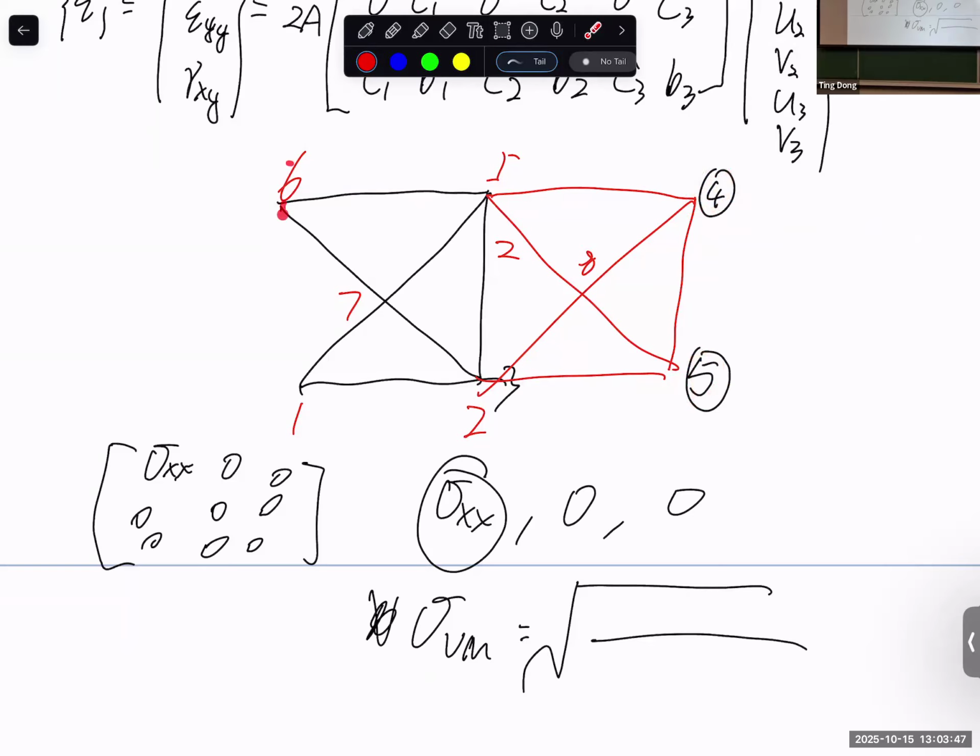And similarly, let's say if this is a boundary condition, you have a definition of the coordinates: node 6, x coordinate, y coordinate, node 1, x coordinate, y coordinate, and you put them in one set, let's say node set 2. And in the boundary condition, I say node set 2, 1, 2, which means you cannot move in x direction and cannot move in the y direction. Makes sense or not? Okay. Any other question?